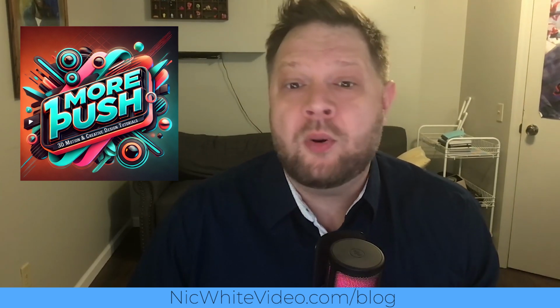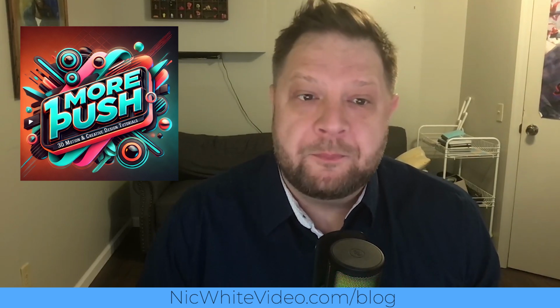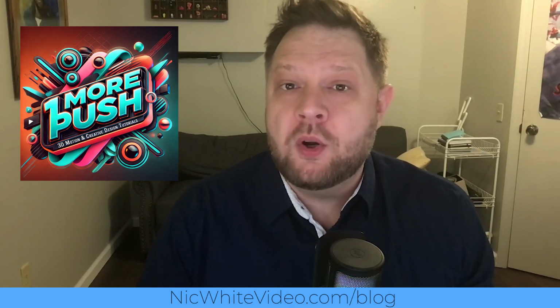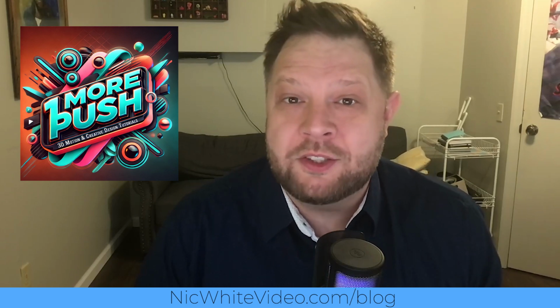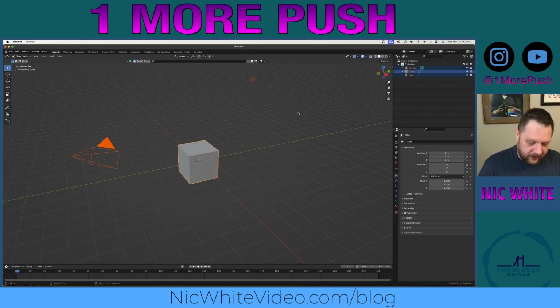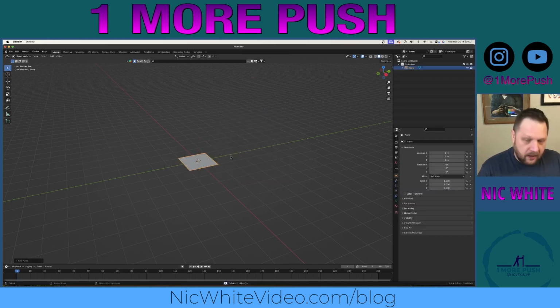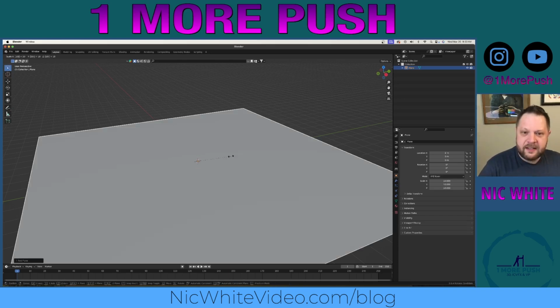Whether you're working on a product animation, a promo, or a visual effects shot, a well-crafted cyc can provide a smooth, professional backdrop for your project. So let's jump right in. We're going to get rid of all of our default assets, and we're going to start with a plane. So let's add a plane. We're going to scale this up by 10 times. There we go. It's nice and large.